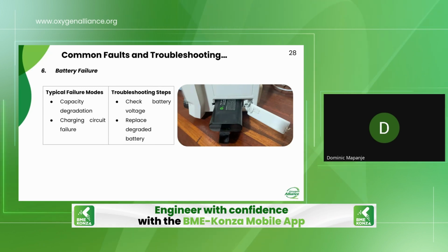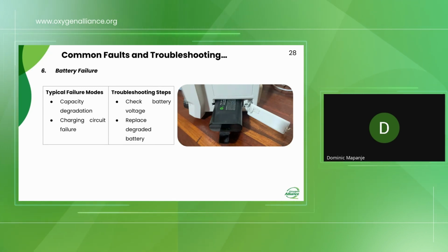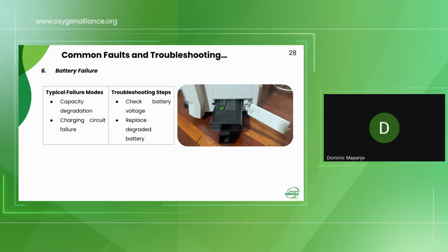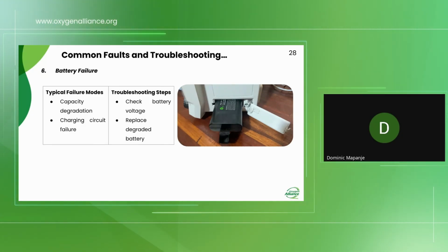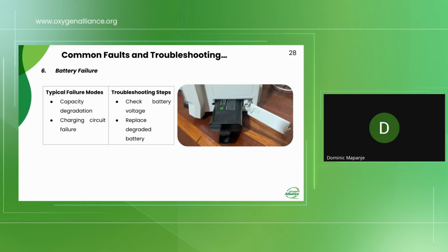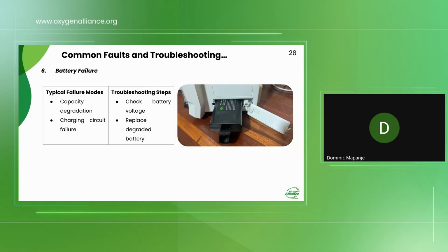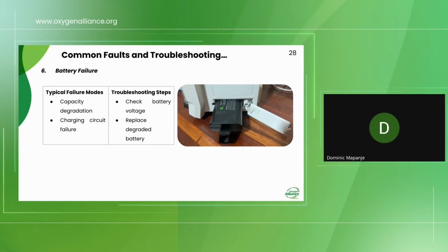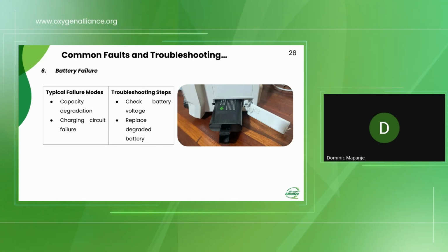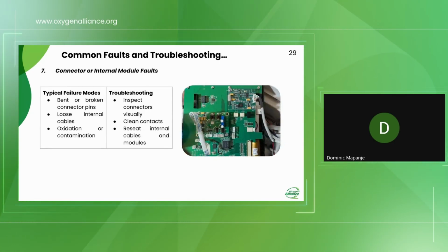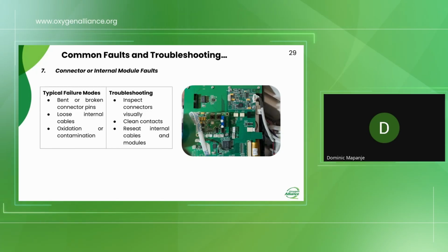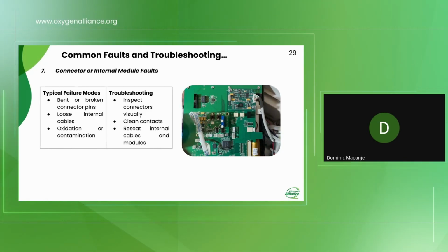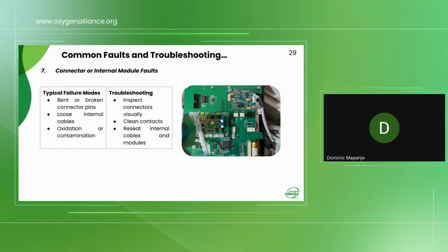You can verify this by just attaching the power to the monitor. You see that it shuts down immediately, or it takes a little time and then shuts down. So you know that the problem is the battery. You have to check the battery voltage, and if it is damaged, you have to replace the damaged battery. And the last common fault presented in this presentation is the connector